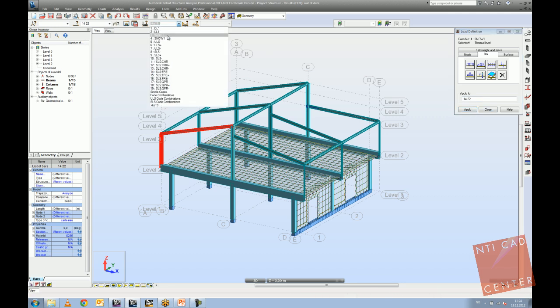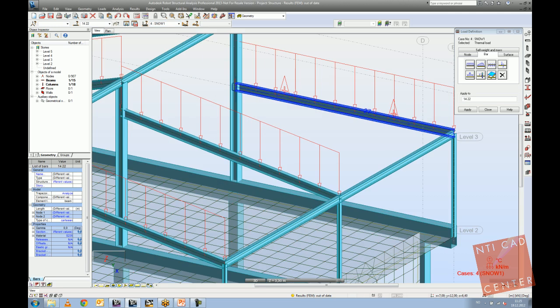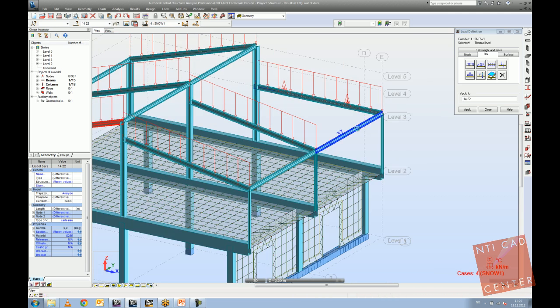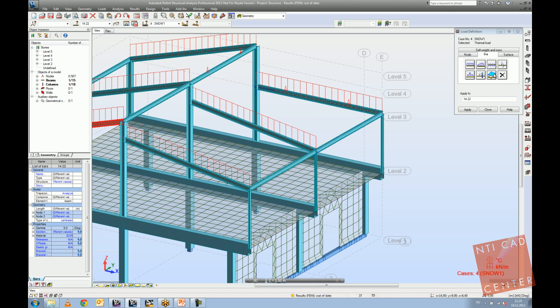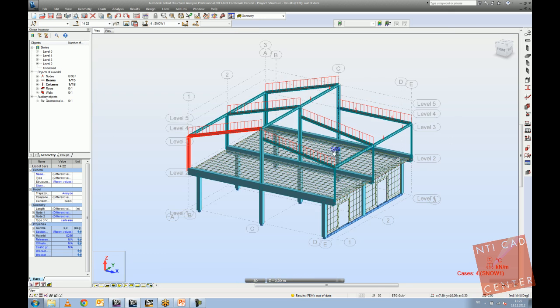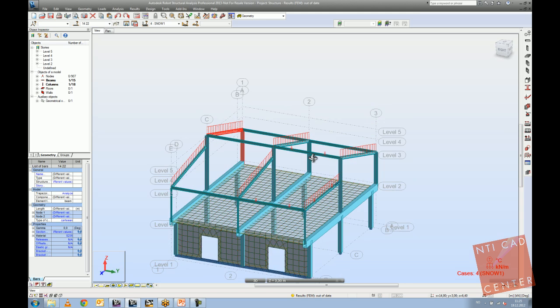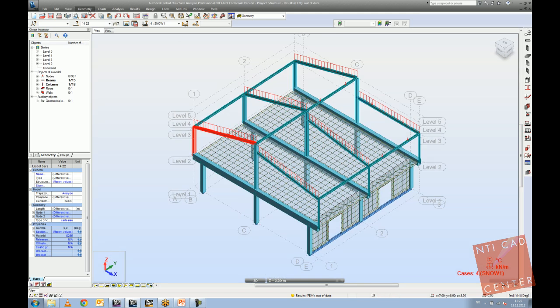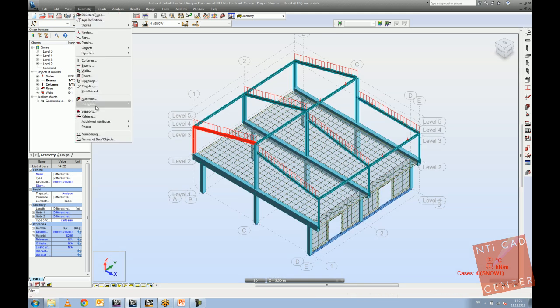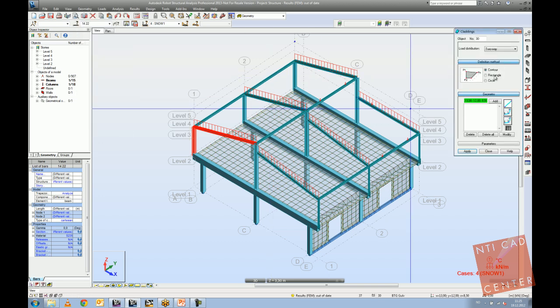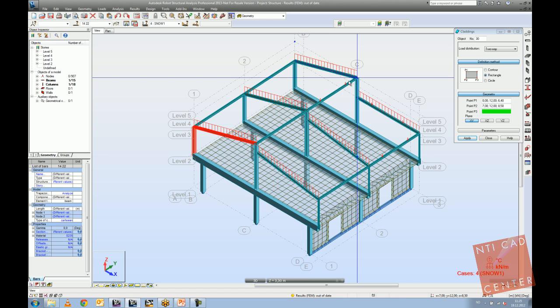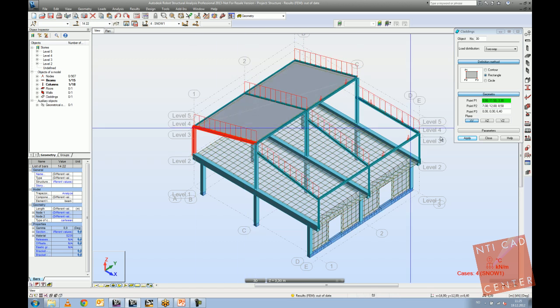okay, I need to look at the snow value. That's interesting. Here, you see that I have a temperature load. Just for sake of clarity, I can add it on the element which didn't have it. So two elements have a load which you don't have in Revit. And then maybe something else. Maybe I will add an additional element which is a cladding, which you again don't have in Revit. So for example, a rectangular element from here to here to here.